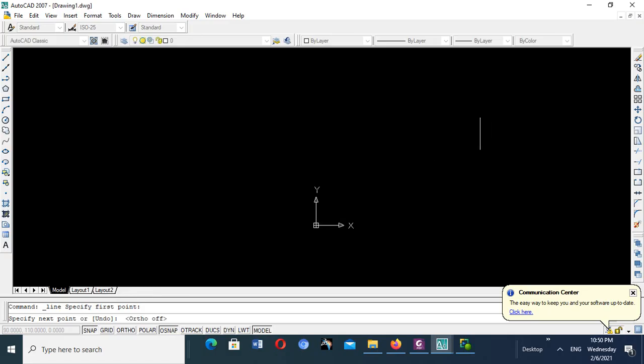I want to draw an inclined line, which is 100 mm in length, inclined at an angle of 45 degrees. So I click, I press shift at the rate, then I write 100, the length of the line. Then immediately after that, I press again shift smaller than sign.